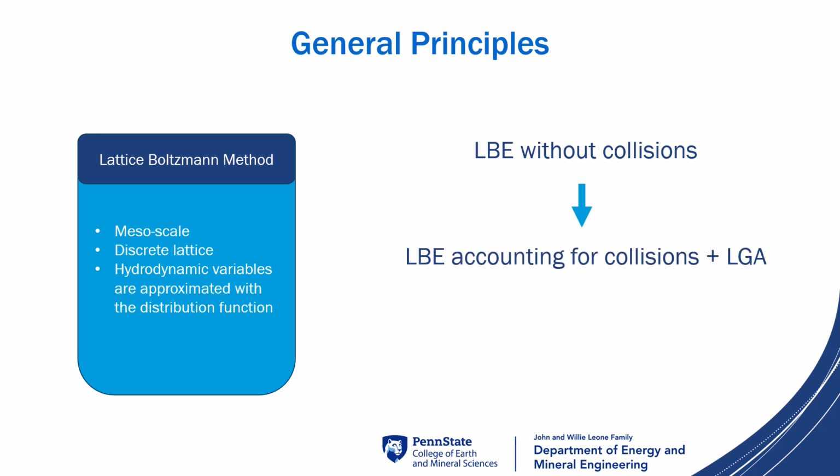The concept of particle motion and the use of the lattice comes from the lattice gas automata, or LGA, but LBM replaces the discrete binary particle tracking of LGA with a smooth statistical approach. Rather than following individual particles, LBM tracks the average particle distribution in each direction.